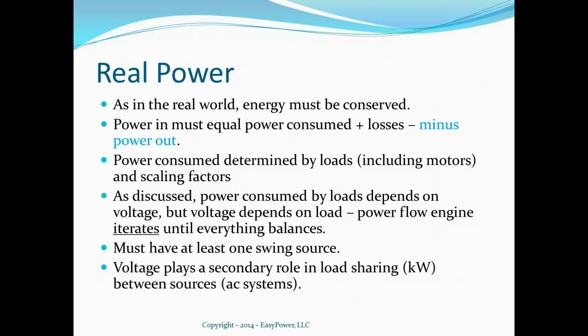Now, the thing that can be a little bit confusing to people when they're dealing with AC power systems is that the voltage is not the primary factor in determining the real power flowing in the system, as opposed to a DC system where it's all dependent on the voltage. In AC systems, that's not the case, because we have reactive power, we have phase angle differences. So the main thing that determines the kW is whatever you specify for your loads, and the losses have to be accounted for. So voltage is not the primary factor.